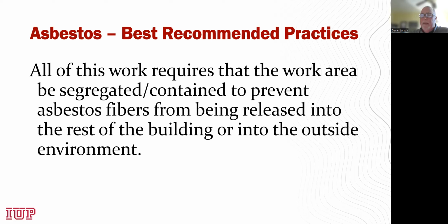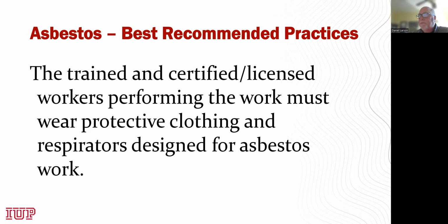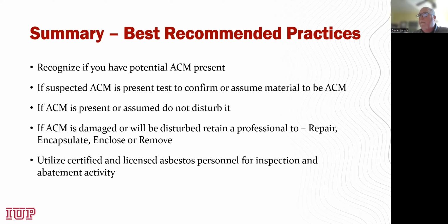If this type of activity is done, in work areas where asbestos repair or remediation is taking place, you have to have segregated areas, containment has to be in place, and you have to take action to prevent any fibers that are released during that activity from getting into other areas of the building or reaching other employees. Again, trained, certified, licensed workers performing the tasks must wear protective clothing and respirators designed for asbestos work.